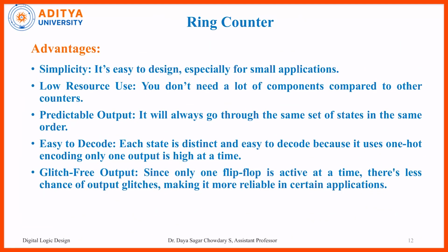Now coming to the advantages of this ring counter. The first one is simplicity, because it is easy to design; the number of stages is increased by increasing the flip-flop count, so for small purposes it is very advantageous. Then low resource use, because we already know only flip-flops are required, not other devices. And predictable output: if we start from 1 0 0 0, the next stage we can simply predict, that is 0 1 0 0.